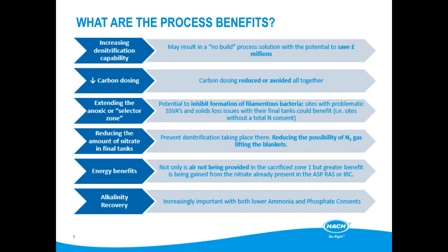Converting Zone 1 to unaerated will not only save on aeration energy, it will also make better use of the nitrate present in the return activated sludge, using the oxygen associated with that nitrate to provide carbonaceous treatment that would have otherwise required electricity.